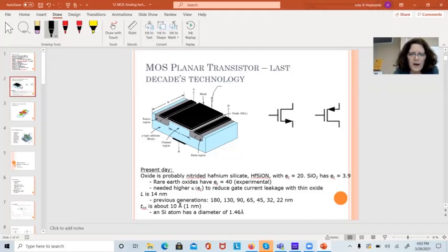The gate is a capacitor. It's a big piece of metal with a very thin oxide and 2 parallel plates. The other plate is the actual substrate of the transistor. It's called a MOS capacitor. I have source and drain diffusions at either end for an N-channel NMOS device. NMOS stands for N-channel metal oxide semiconductor. I'm answering some of your questions from the quiz as I go along.